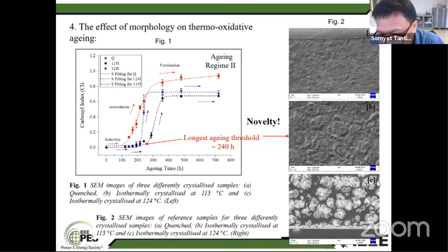And then in figure C, this is polyethylene produced with the crystallization process at 124 degrees Celsius for 4 hours. The crystal will be bigger than the others, about 20 microns. And then you could see the black space surrounding the white crystal here. This is the amorphous region, containing low-order polymer chains.